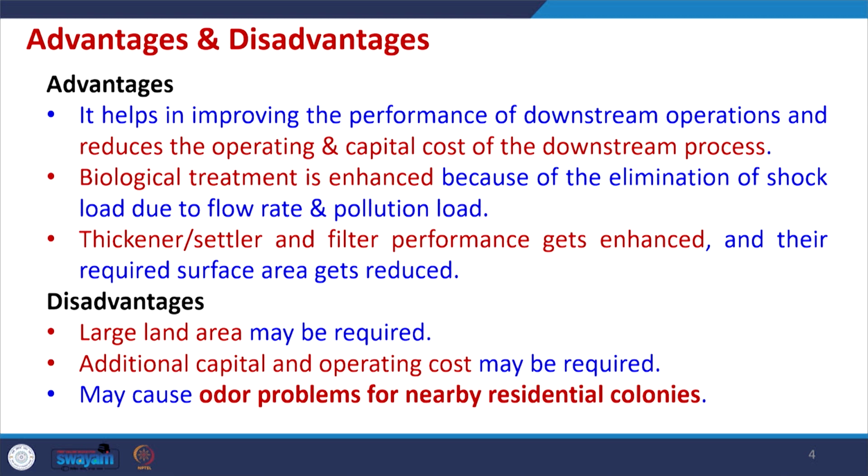Biological treatment efficiencies get enhanced because of the elimination of shock load due to flow rate or the pollution load. The thickener, oblique settler and filter performance also get enhanced, and their required surface area gets reduced.